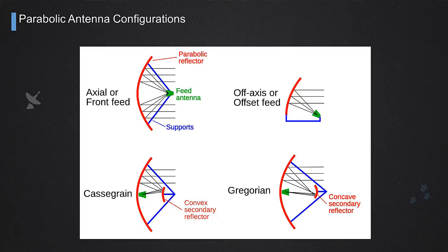We'll see that many times the antenna configurations on board the satellite are chosen depending on the mechanical constraints you have. You have to accommodate this antenna on the spacecraft, and depending on the dimension of the antenna and the configuration of the spacecraft, you might find one solution or the other. So there is always a compromise in terms of mechanical constraints, accommodation constraints, and of course also electrical or radiated performance and constraints.